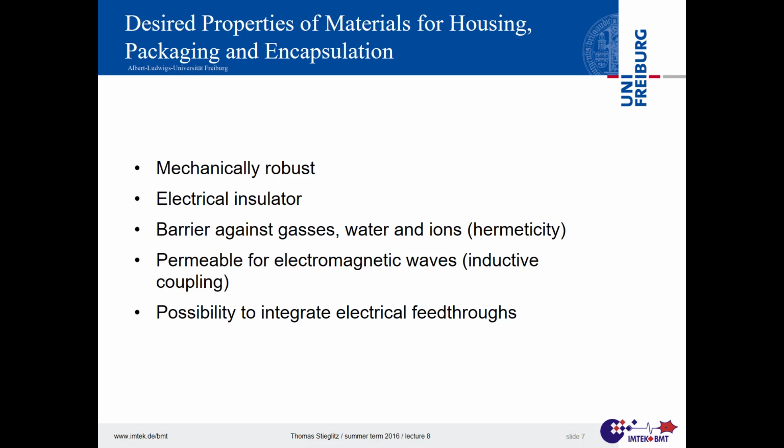Then osmosis comes into game, right? So if you have a little bit of salt on one side and no salt on the other side, then osmosis drags water. If there's no room for the water to go, then it pushes on the insulation layer, and if the force of the osmosis is larger than the adhesion force, then it just pushes all your encapsulation away.